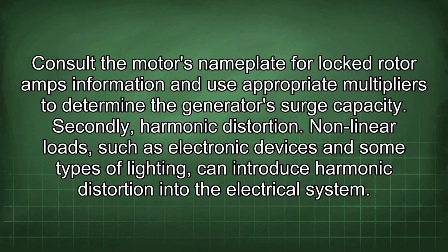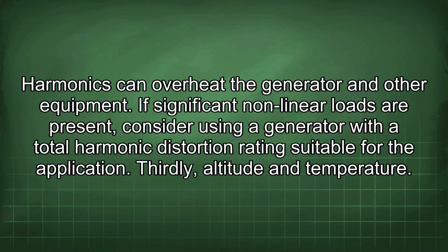Secondly, harmonic distortion. Nonlinear loads such as electronic devices and some types of lighting can introduce harmonic distortion into the electrical system. Harmonics can overheat the generator and other equipment. If significant nonlinear loads are present, consider using a generator with a total harmonic distortion rating suitable for the application.